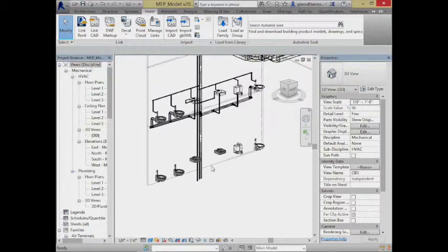Okay, so how big should that line be is one question you might ask. It really depends on how many fixtures you have back upstream from it. With only 2 toilets, if it's 4-inch outputs, this could probably still be 4 inches. If I had 12 toilets over here, it might have to actually be a little bit bigger. There's this notion of, if everyone flushed simultaneously, what's the worst case scenario you might run into? But often this will be like 4 inches.